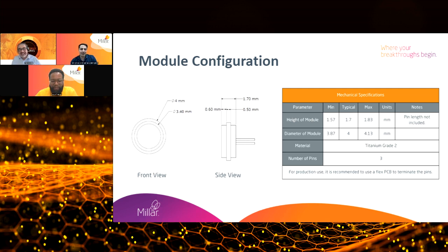Yeah, sure. Our TiSense is a half-bridge sensor, meaning that it includes two 3 kilo-ohm resistors inside it. Therefore, if you want to integrate it with your system, you need additional 3 kilo-ohm resistors to complete the bridge and measure the differential voltage.